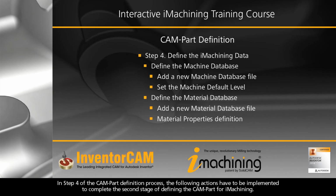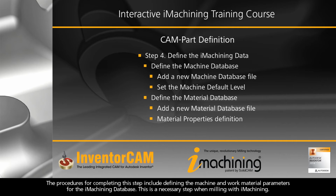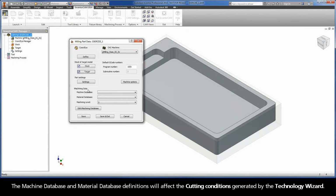In Step 4 of the CAM part definition process, the following actions have to be implemented to complete the second stage of defining the CAM part for iMachining. The procedures for completing this step include defining the machine and work material parameters for the iMachining database. This is a necessary step when milling with iMachining. The machine database and material database definitions will affect the cutting conditions generated by the technology wizard.